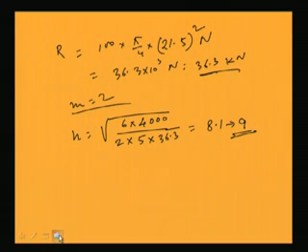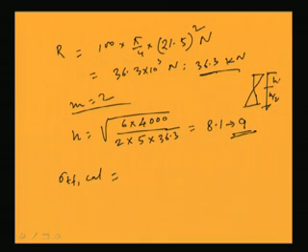So, what we will do now? Now, we have to find out sigma Tf calculated. For hot rivets where the initial tension is considered, we have assumed that the neutral axis is at the h by 2 distance, that means at the middle position. This is h by 2, this is h by 2. So, this is the neutral axis. So, with that we have found an equation earlier that sigma Tf calculated can be found out from this equation.